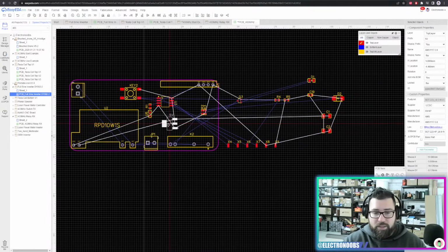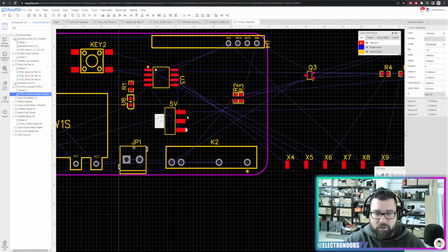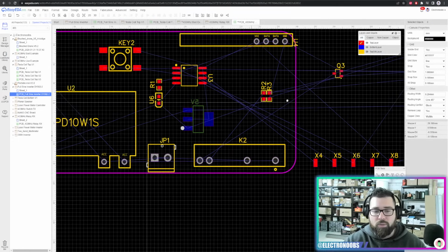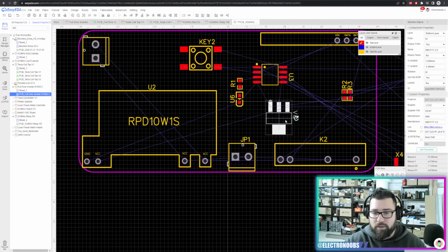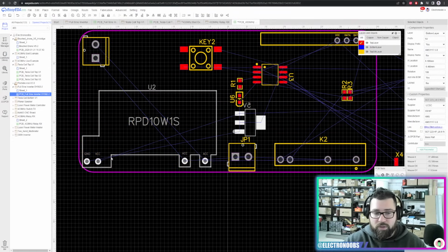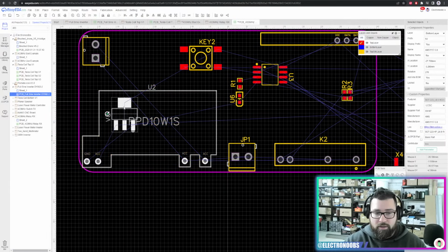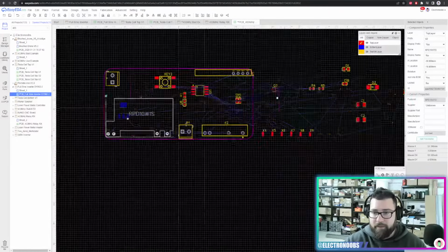The voltage regulator, I will place this voltage regulator on the other side of the PCB. So all you have to do is select it. You go here, and change from top layer to bottom layer, and it will change the color to blue. So that will be here. We know that we'll have 12 volts from here, so we can place it here, right? Like this.